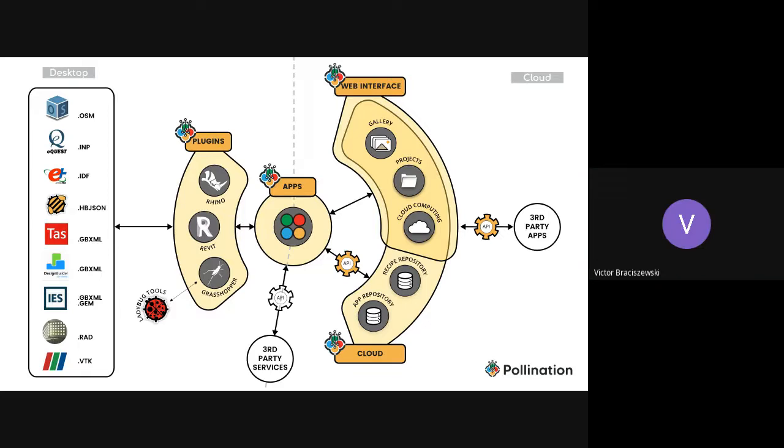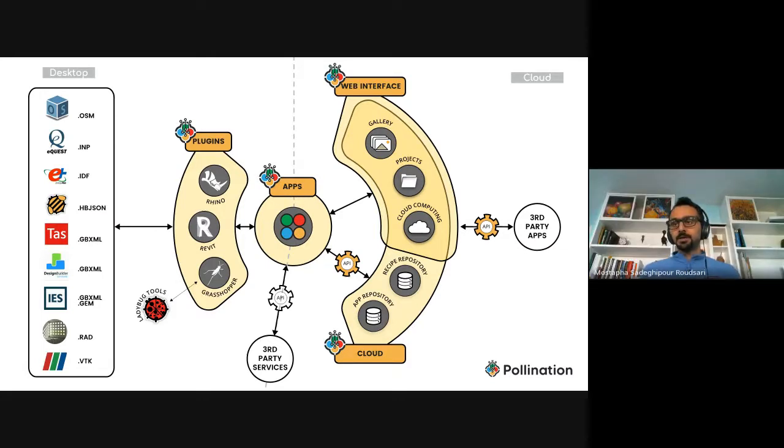The other way around, if you're in Pollination and Grasshopper, is exporting it out and importing it into Design Builder. With Design Builder, I have tried GBXML, and that has been fairly successful, but I have not tried IDF. What I understand is that if you do IDF, Design Builder translates IDF to GBXML and then has an importer from GBXML to Design Builder. So maybe a better workflow is to export GBXML from Ladybug Tools, or Pollination, and try to go to Design Builder.